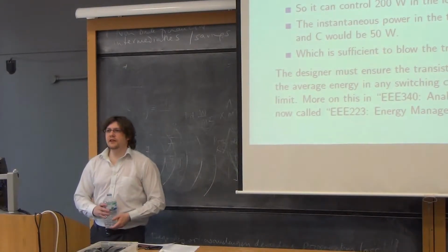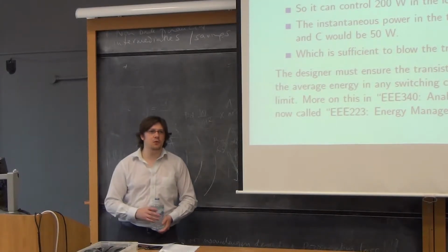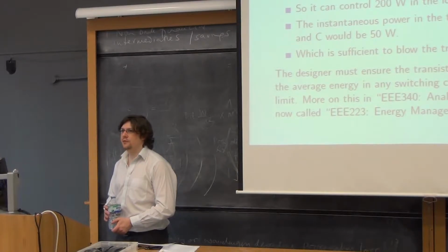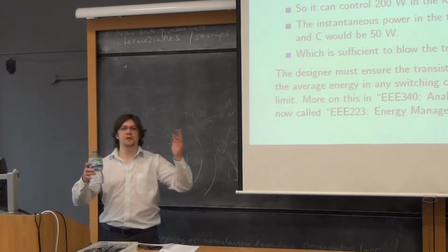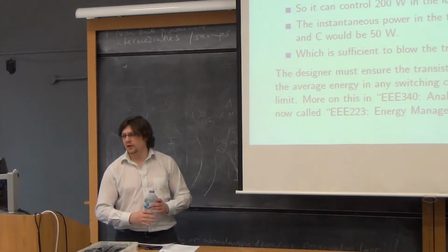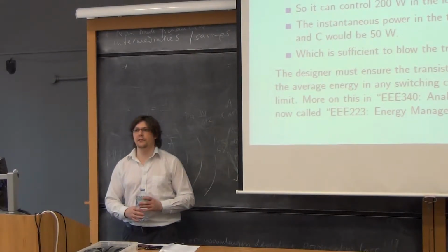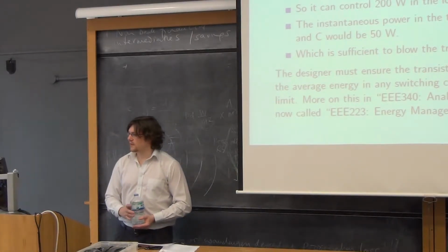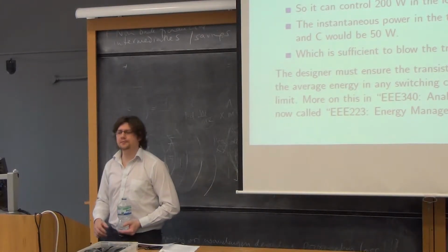But it can only handle a watt, and if you do actually put a watt through this transistor, it will get up to about 170 degrees C. So 50 watts, it'll just pop and there'll be some smoke. And that's where the idea that electronics runs on smoke comes from, because when you blow it up you let the smoke out, and that's why it's broken, because the smoke has escaped. There's a lot of evidence to suggest that's not the case.